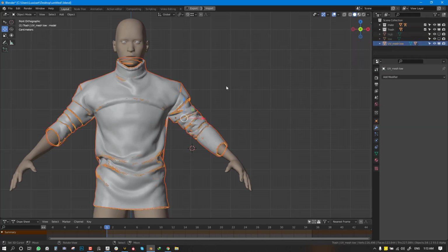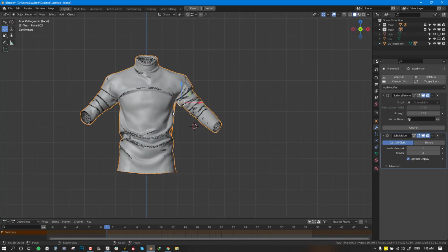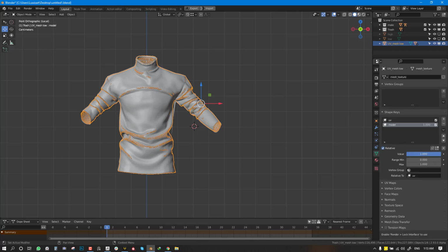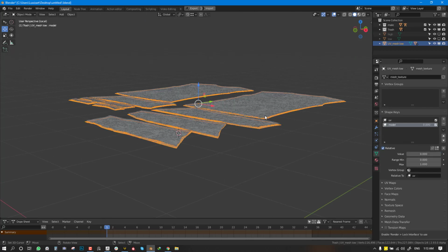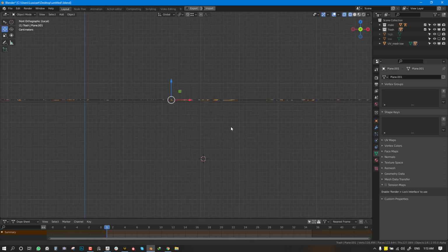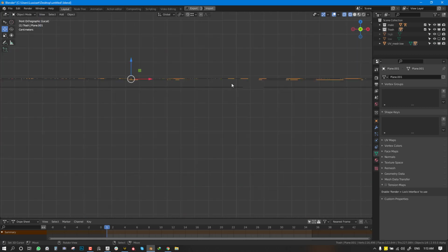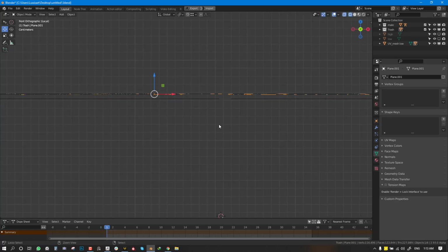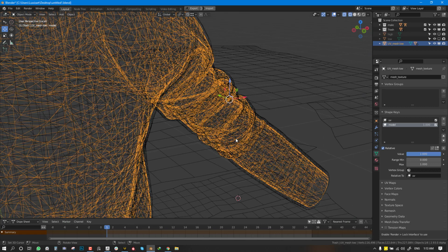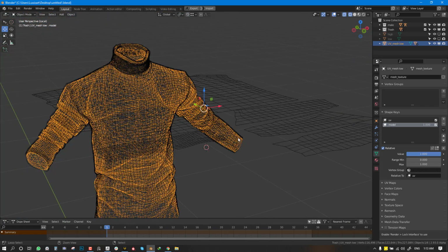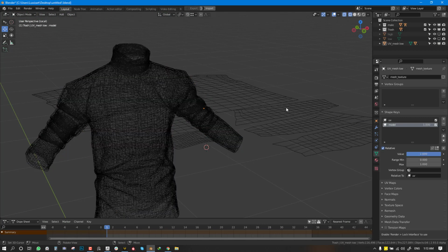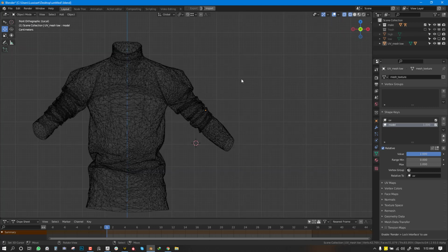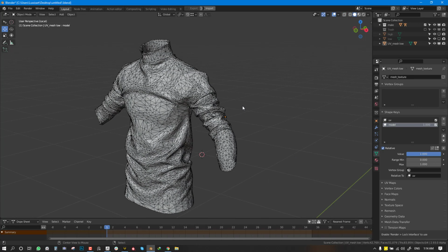One thing you should bear in mind for combining them: if I select this mesh, you want to make sure that they are in the same position. You want to make sure it aligns perfectly on the same line. I had to even redo some stuff because I failed to do that. And if you don't do that, what you will get is the mesh looking bloated, which is definitely far from what we want.